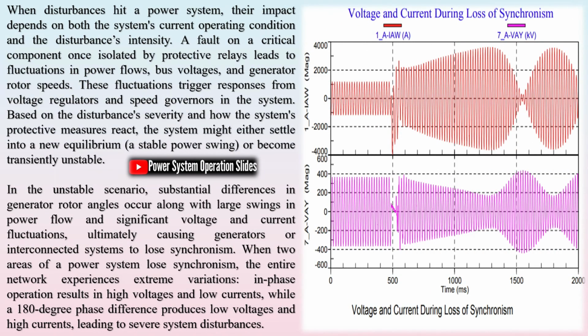Out-of-step tripping: this targets predetermined network locations to disconnect system areas that are experiencing unstable power swings, thereby preventing further outages. Out-of-step blocking: this scheme ensures that distance relays or similar protective devices do not operate incorrectly during power swings, restricting separation actions only to the desired locations.